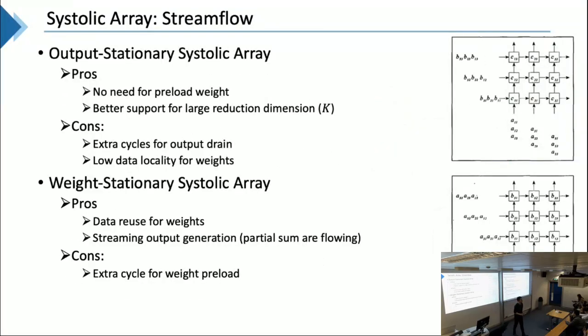So here, the other thing I want to mention is that different scenarios and matrix multiplications with different dimensions actually prefer different dataflows. Here, I compare the output stationary systolic array with the weight stationary systolic array. The advantage of the output stationary array is you don't need to preload your weights.